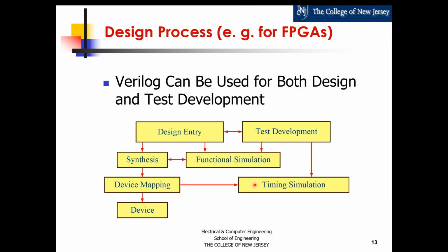And you can do timing simulation of the functional simulation, but there are better ways, called static timing simulation. Mainly if you're doing synchronous design, which is what you should be doing anyways. So that's part of your testing as well. Once this is clean, and you can even regress your functional simulation with timing, once all this is clean, then you can, from device mapping, actually transfer that functionality and get your device done.